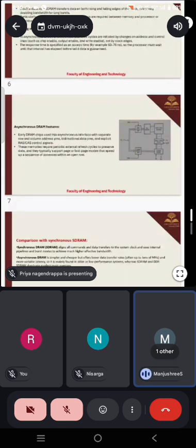The column decoder connects the sense or write operations, and the data is given to the column decoder as D in, and the column decoder sends the data out as D out. CS stands for chip select, and R/W are the read and write operations. Thank you.